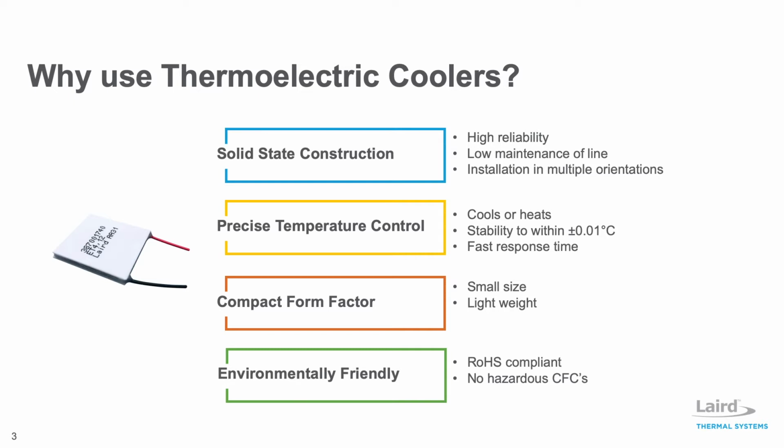Thermoelectric coolers have several advantages over alternative cooling technologies. They have no moving parts, so the solid-state construction results in high reliability and units can be mounted in any orientation. Thermoelectrics are able to heat and cool by simply reversing the polarity, which changes the direction of heat transfer.